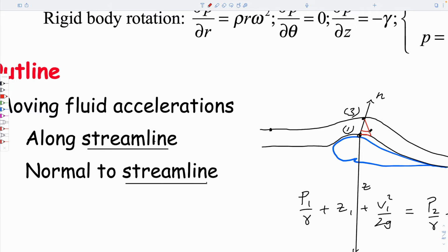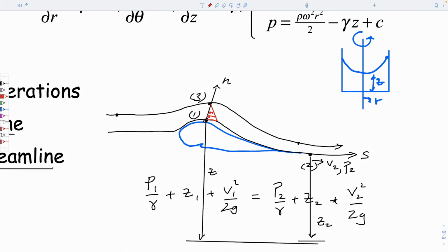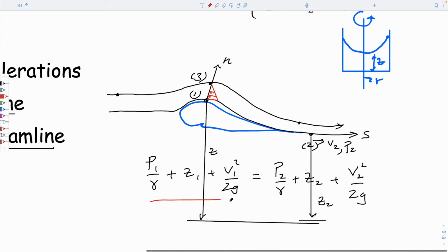we can imagine that there's a change in pressure, because if we go within a fluid in a static swimming pool, from the surface down to the bottom of the pool, we know that the pressure at the bottom will be higher. And so we can think of this little trapezoid or triangular distribution of fluid pressures. And so the other thing we might like to do is to do exactly what we've done here and write the conditions at point number 1 and point number 2 to be able to determine what an unknown value is at 2, say.